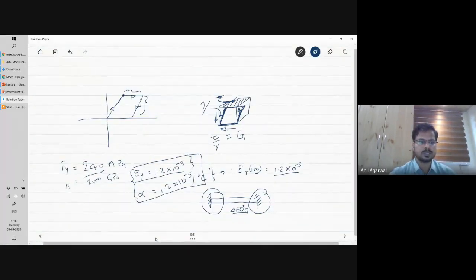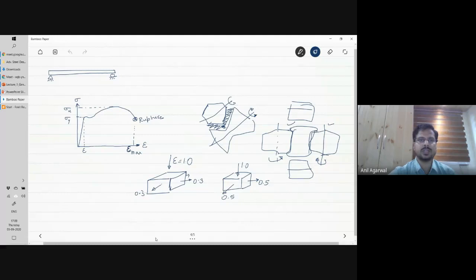We had discussed this typical stress strain behavior here, right? So you can see this plot, right? This is a typical coupon test. So what we do is, let's say I have an I section. An I section has several plates. So it can be a hot rolled section, it can be a welded section. Whether it's a welded section or a hot rolled section, there are coded provisions which tell you how to do the test. They tell you where to cut the sample from. So first you are required to cut a strip of this plate. I can't draw it very clearly. So let's say I cut this strip. You can see this strip that I have cut from this. So you cut that strip.